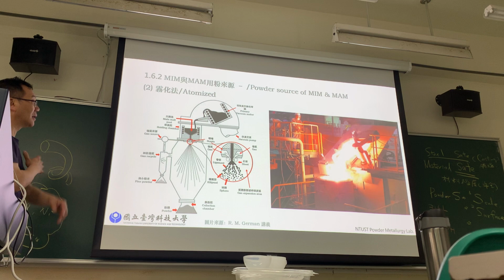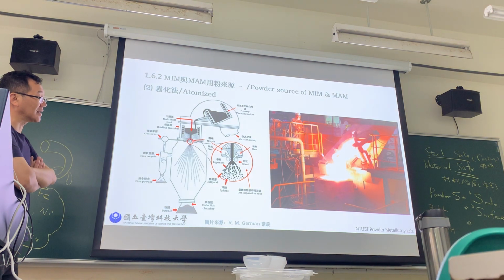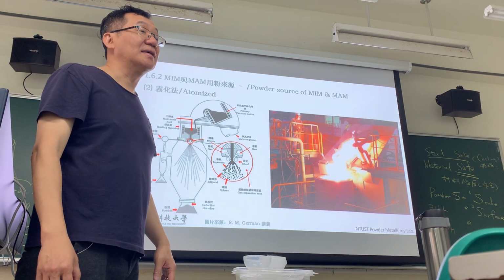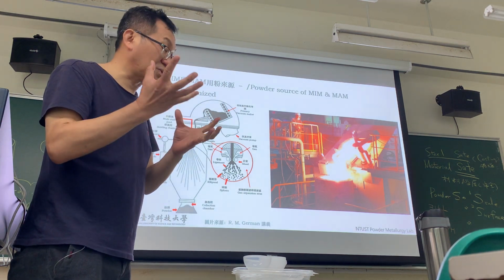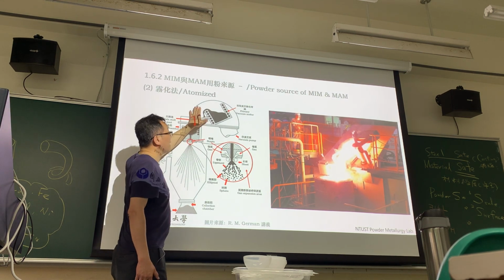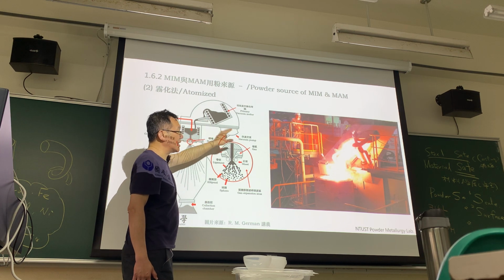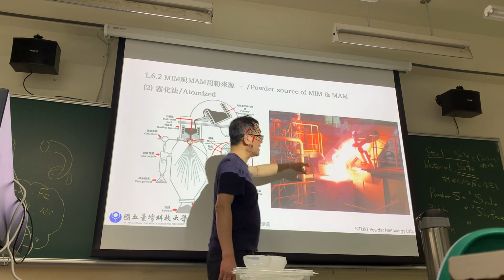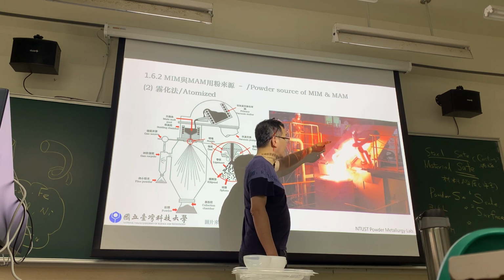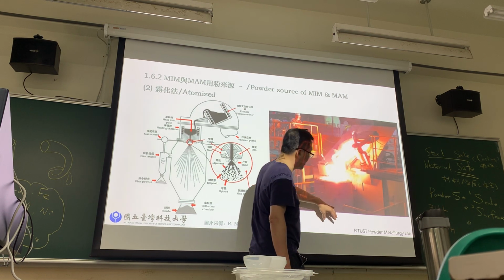This second picture is what we call atomization. The atomization process is easier to understand. It's melting the metal like soup, with everything inside. Then it goes to a tank and is sprayed. Sometimes we make some covering for the bucket to prevent oxidation. But normally for stainless, we don't need this cover because stainless is not afraid of oxidation. So it can be in the air, no problem. And we pour into this nozzle in here and spray.